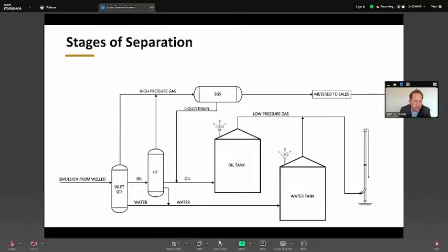So in this situation, you got your inlet separation. So that first stage of separation, you got your water going straight to the tank. So whatever flash is in that water, whatever vapor entrainment or gas entrainment's in that water, it's whatever is at that first stage is its peak potential. And then each level of separation will pull more gas off and send it to sales. So then we can determine, okay, what's the maximum amount of flash going to the tanks? In this situation, it would be the heater treater that's going.